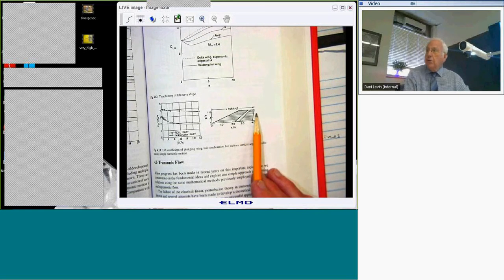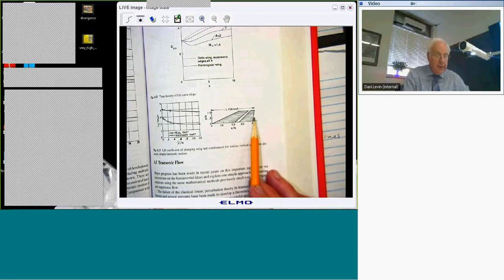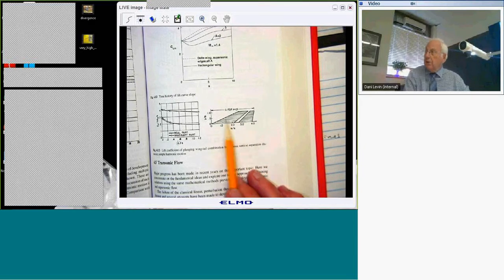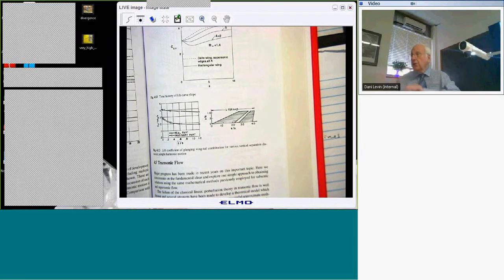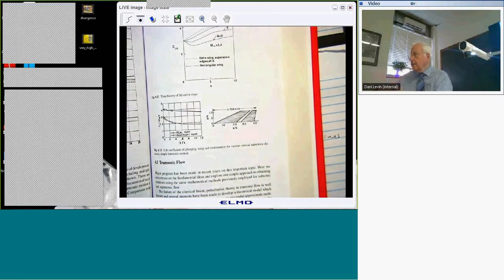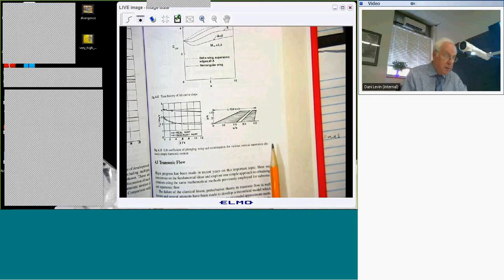This is the horizontal tail, right? And these things are close enough, right? This distance is a small fraction of the chord of either of these surfaces. So there's interference. So when I analyze this, I have to analyze it as a composite system, right? And I have to allow for the fact that there's interference between these two.